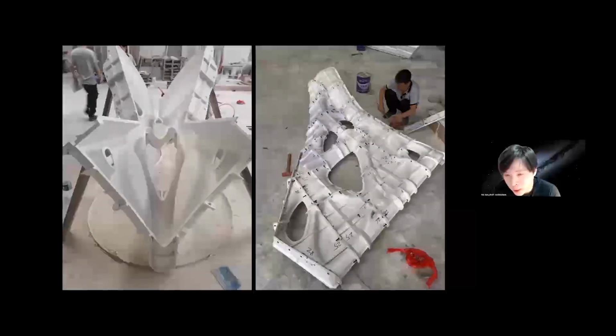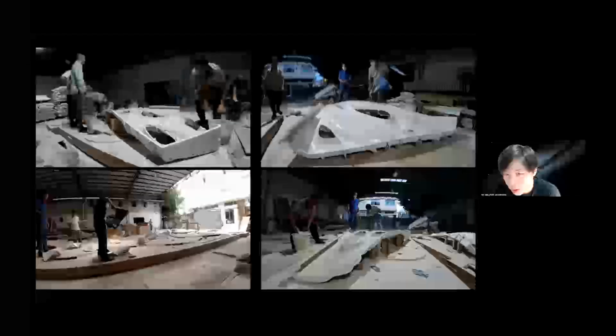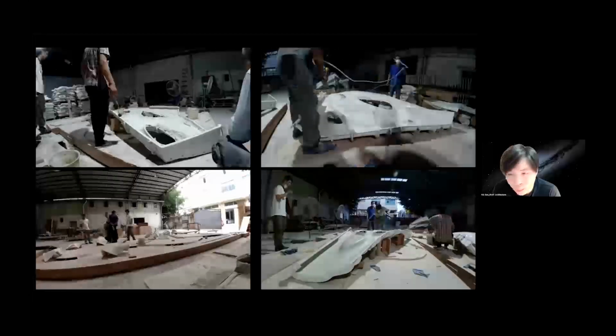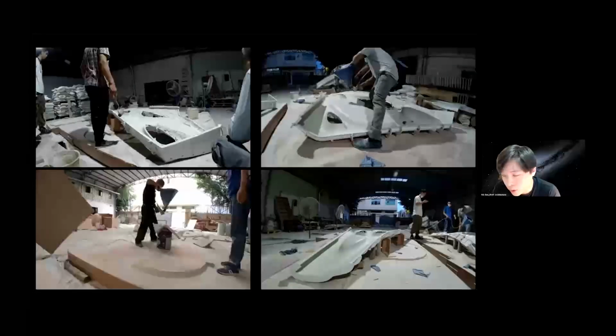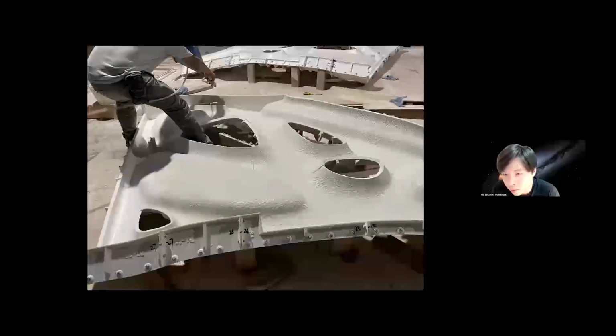This is the mold design. The left one is the middle part, and the right one is the 2 side parts. We are using a new technique to spray the UHPC concrete on the surface. You can see the workers helping us spray the UHPC, which is high performance concrete, on the surface of the mold. This is the first layer. The first layer is just normal concrete, not UHPC, because we want to keep the surface smooth.